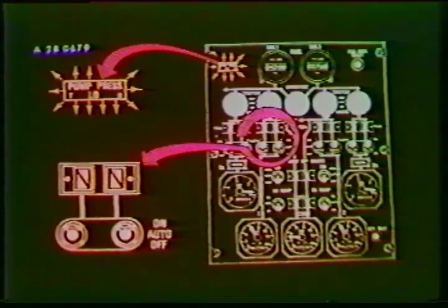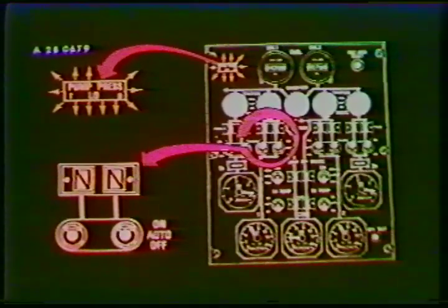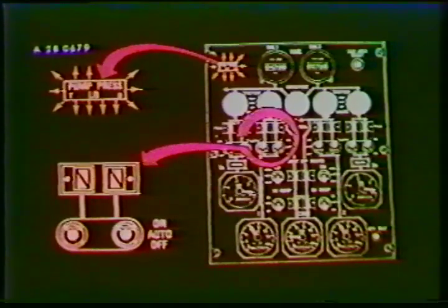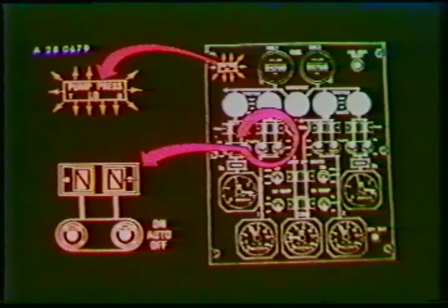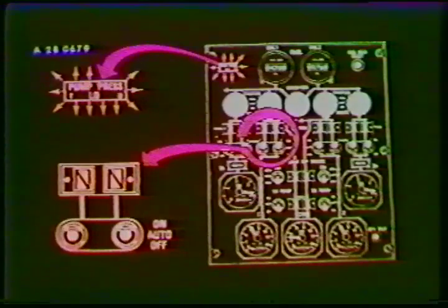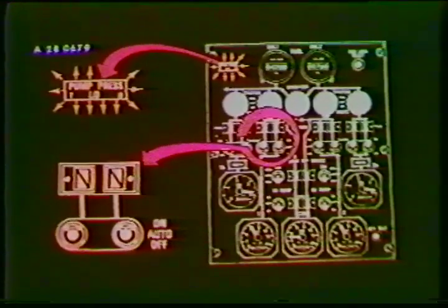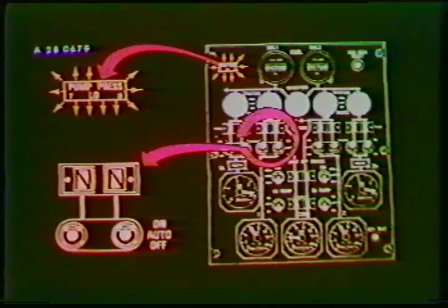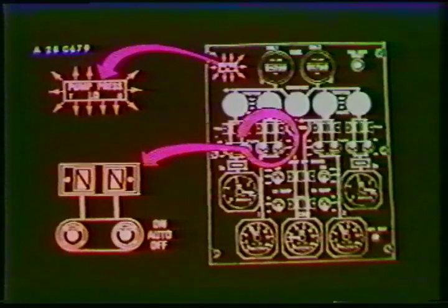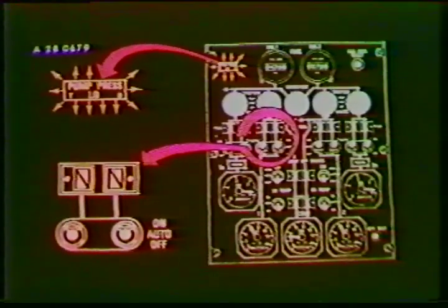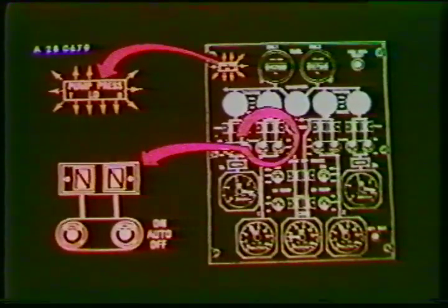Note that on the upper left corner of the panel is a warning light labeled Pump Press Low. It illuminates when the pressure output of a pump is low. The magnetic indicator of the faulty pump will simultaneously turn to amber. This occurs, for instance, when the inner tanks are empty. The warning disappears when the pump switch is set to off.